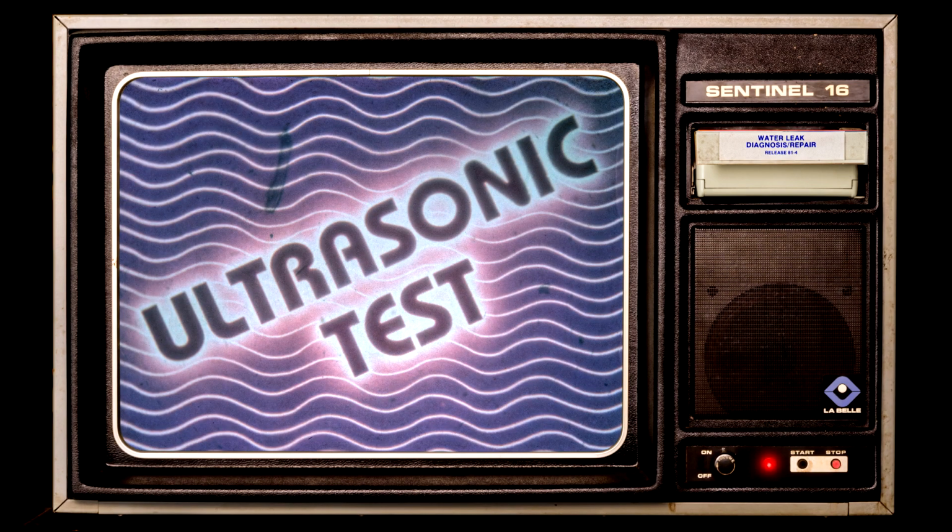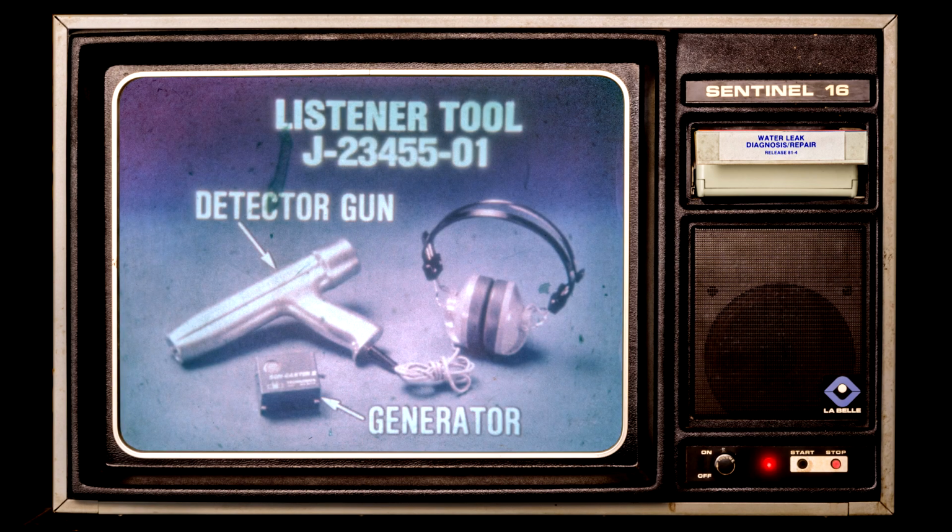If a visual inspection and light test don't direct you to the leak point, there's another diagnostic check you should use, the ultrasonic test. To perform this test, you'll need a special tool, a listener tool, which consists of a detector gun and an ultrasonic generator. This tool is available through the AMC tool program.